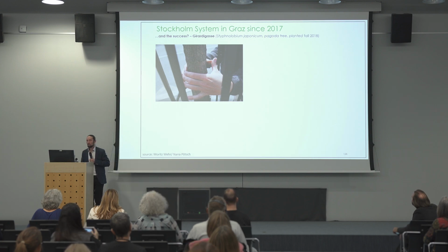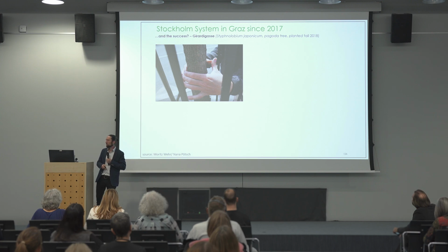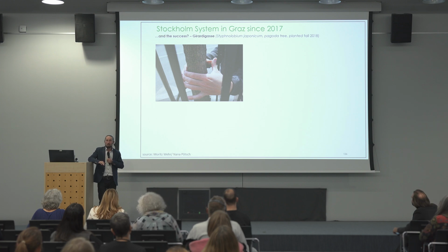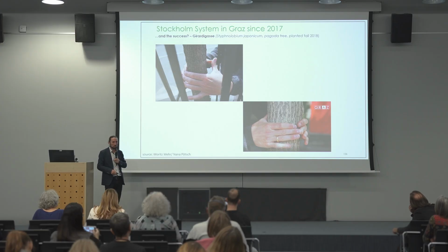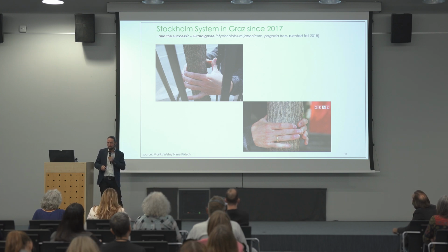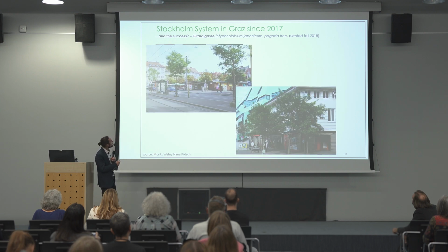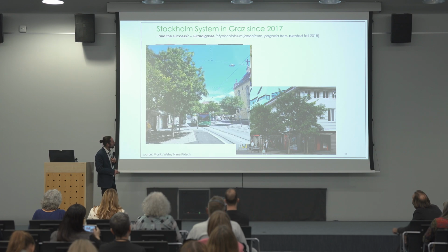Another example from the Girardigasse, with a pagoda tree, Styphnolobium. There in the tram station we tried to make the tree pit bigger with a concrete system, but we didn't infiltrate water. And on the other side of the street, we planted a tree in the Stockholm system. Three years later, I put my fingers around the trunks, and it was incredible, the difference between the two trunks. And you see it also on the crowns.